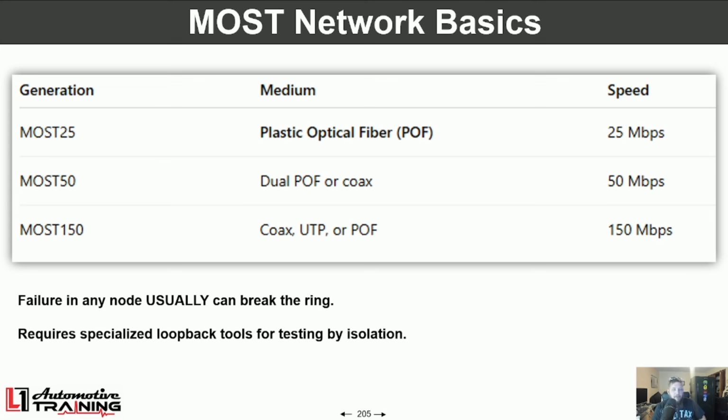they are coax, but most of them are essentially twisted pair wires as well. So they're actual regular style wires that you can back probe and look at and deal with. So it's not some super exotic situation unless you are dealing with Jaguar, Land Rover, BMW. And then the exoticness of them is because it's fiber optic type cable, plastic optic fiber, and they are exotic in design for automobiles, but not in cost.